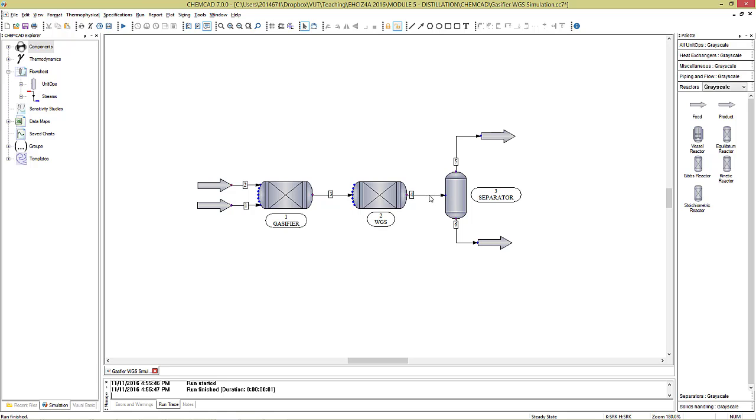Then what you would essentially do here is you would look at your H2 to CO ratio. As you can see, our carbon monoxide is 6, our hydrogen is 17. This is still way above 2, because if it was 2, our hydrogen was just supposed to be around 12 point something, 12.4, because there we have 6.2.